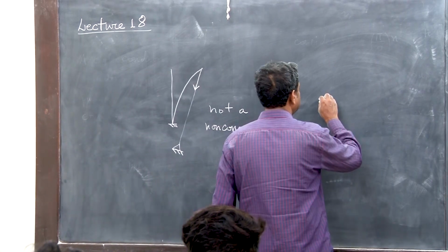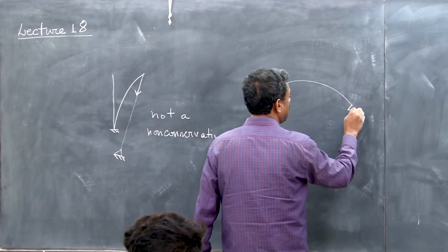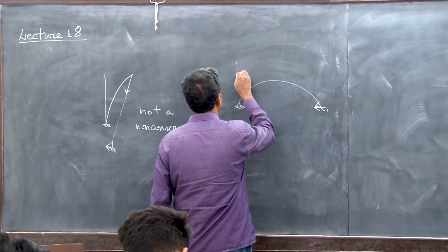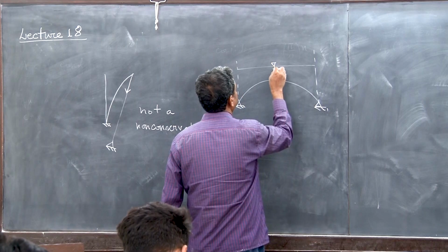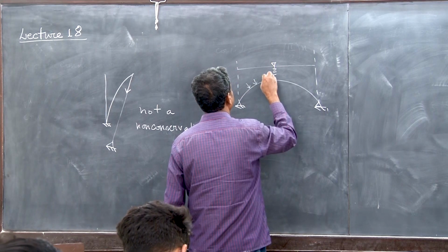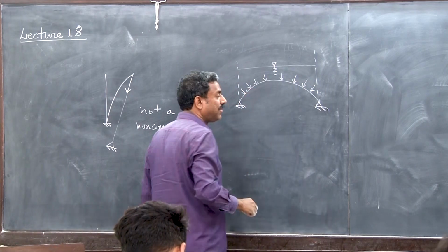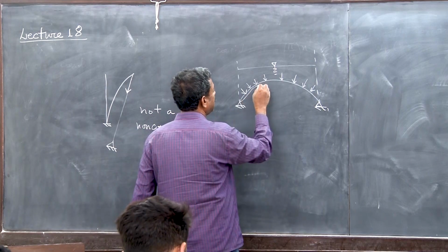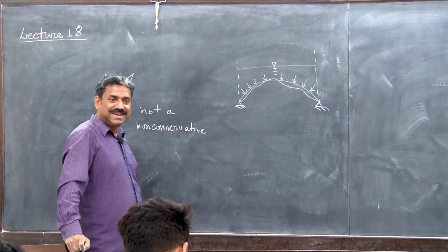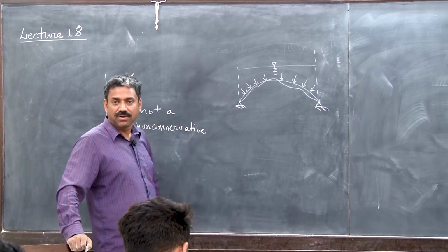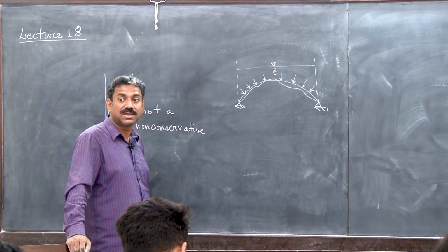Similarly, another example: consider a shell subjected to hydrostatic forces. Hydrostatic force is always perpendicular to the surface. Whenever it deforms under this force, the force will also be perpendicular to the deformed surface. So you may think that this is also a follower force, because it follows the deformation of the surface.